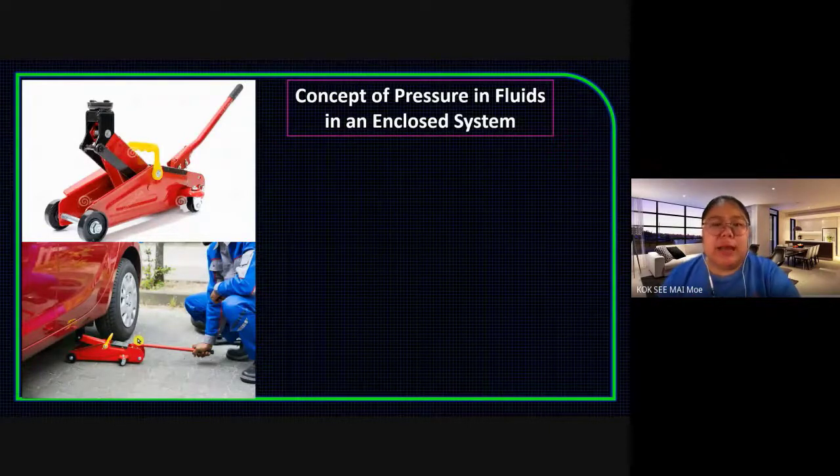So inside there, what helps you to lift the car? Actually, it's the fluid. The liquid is moving. When the liquid moves to the output, there is another, big piston to push. It produces the bigger output force, then it can lift the car. So let's explain.